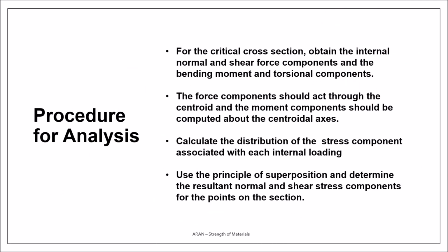In summary, the procedure for combined loading analysis: find the critical section, find the normal and shear forces and the bending and torsional components of moments. That's number one. That's important.